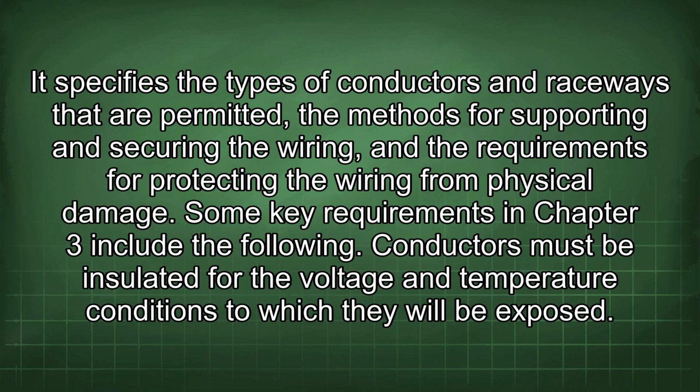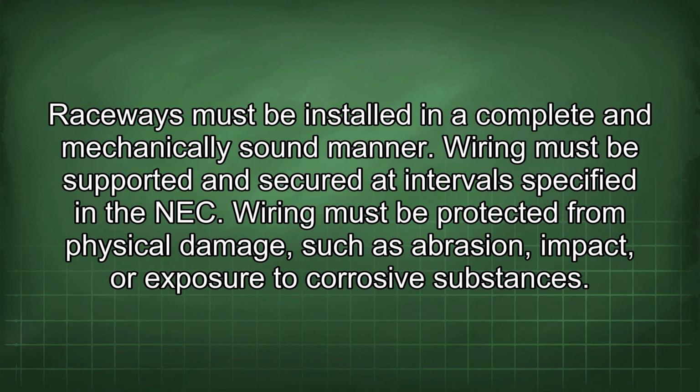Some key requirements in Chapter 3 include the following. Conductors must be insulated for the voltage and temperature conditions to which they will be exposed. Raceways must be installed in a complete and mechanically sound manner. Wiring must be supported and secured at intervals specified in the NEC. Wiring must be protected from physical damage such as abrasion, impact, or exposure to corrosive substances.